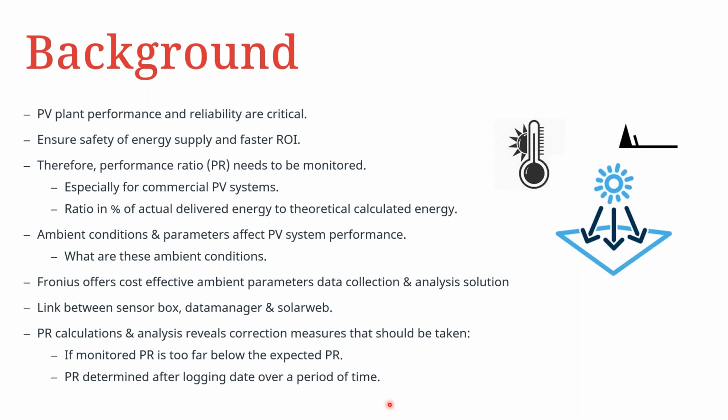So you cannot install a system today and in a few days or in a few weeks you want to do a performance ratio analysis. So this would be typically something in the region of maybe 6 months or a year after installation. But for that, therefore, you need data accumulated as far as these ambient parameters are concerned over that particular duration.